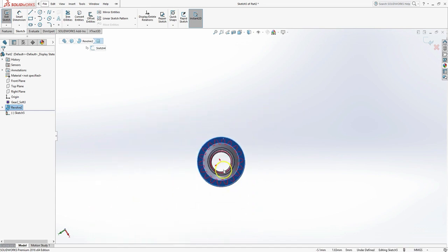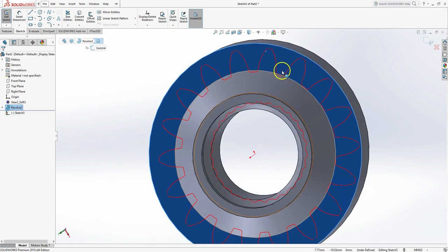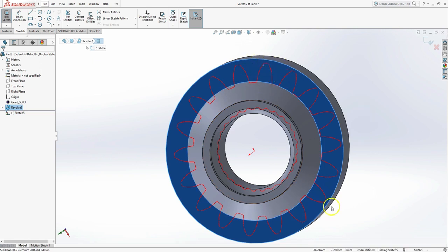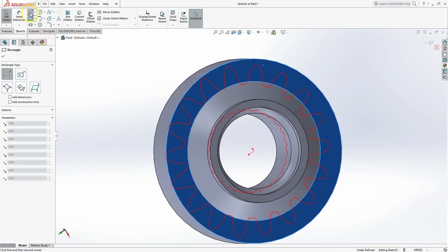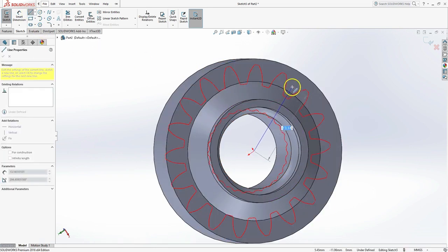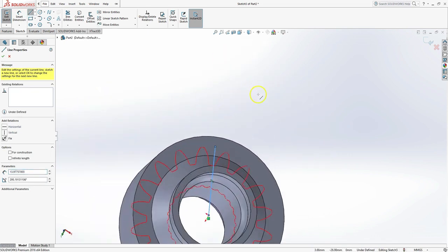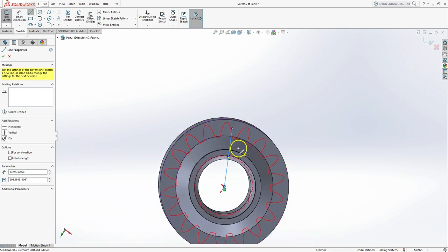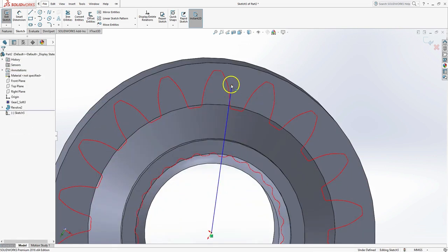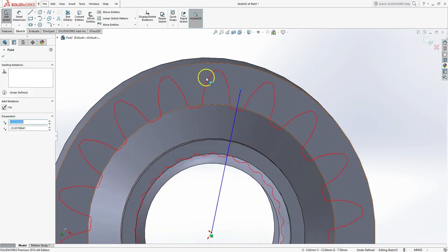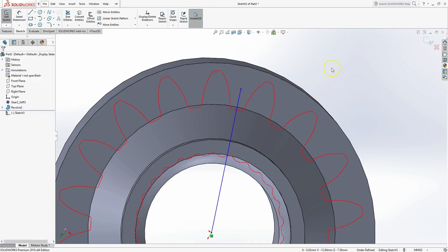And so the way that I like to make teeth, and I'll just kind of walk you through this, is I like to take a single tooth and then pattern it around the perimeter. And the easiest way to do that is to draw a line. And let's draw a symmetry line. It doesn't really matter which tooth you use. If you're working with 3D scan data, sometimes it's best to just get the cleanest scanned tooth. Sometimes they scan really well. Sometimes they're harder to see. They might get noisy or gummy.